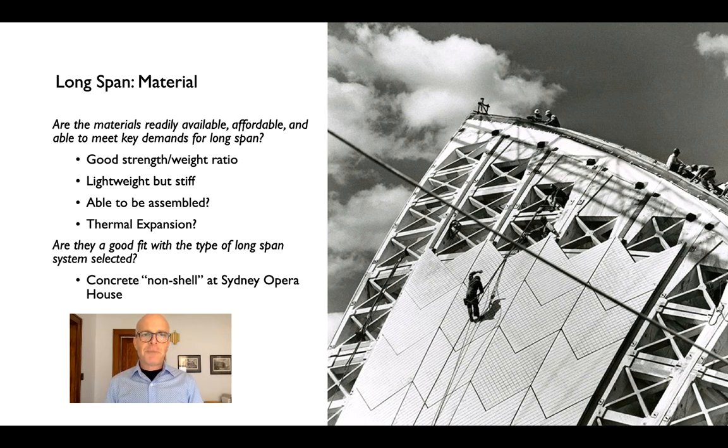And as I mentioned before, thinking about thermal expansion, steel expands and contracts much more in hot and cold weather than concrete does. And so if we're going with steel, we have to worry not only about stiffness, but we also have to think more about how that live structure is going to grow and shrink over the course of a typical year, weather-wise.